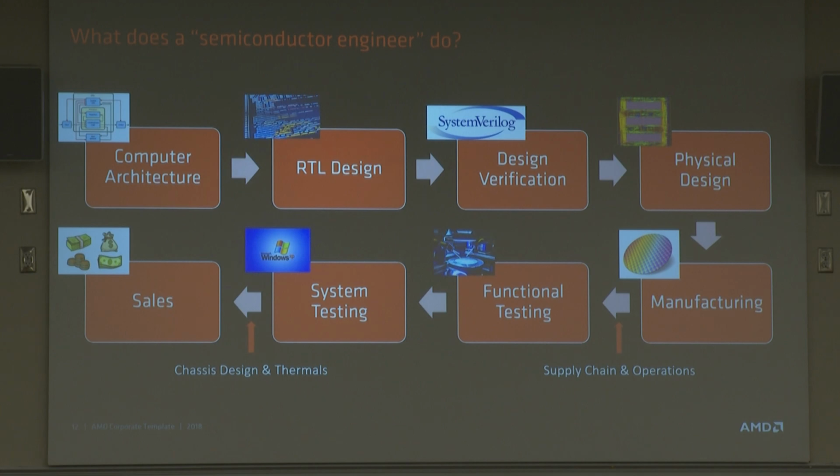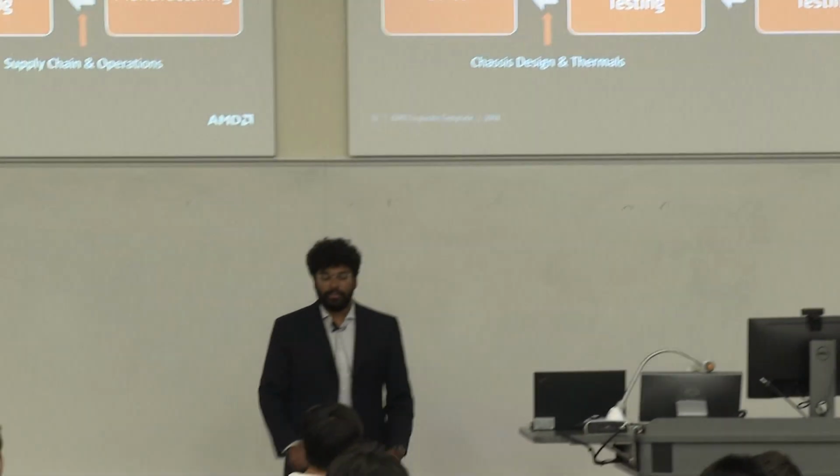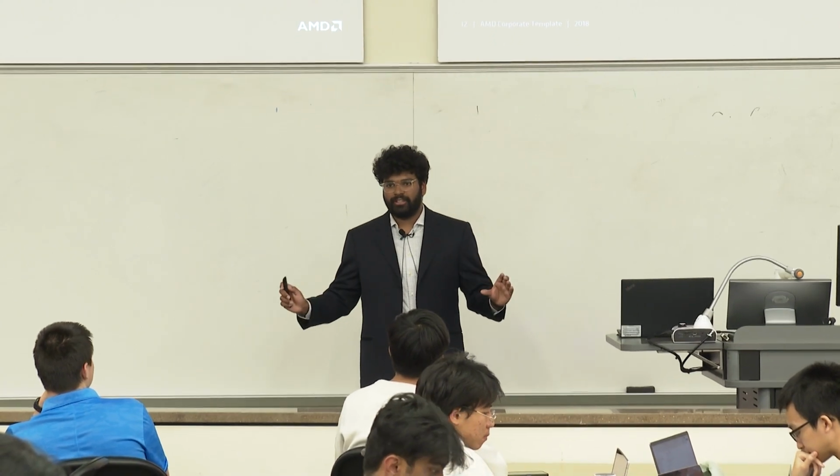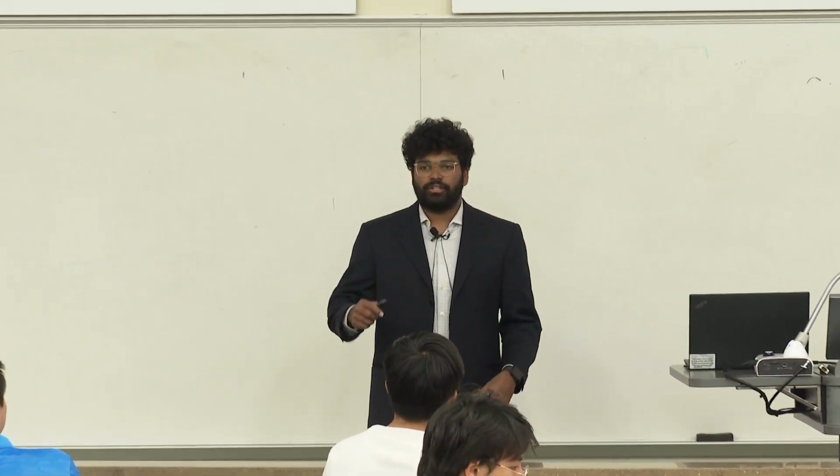Next, you have design verification. Once you have this structure in place, once you have it simulated, does it work? These are the people who are basically trying to break your simulation, right? You have this code that seems to work perfectly fine, and now you need to make sure: are there any bugs in it? Are there any bugs that you can manually introduce? Basically a DV engineer's job is to break what the RTL engineer did, right?